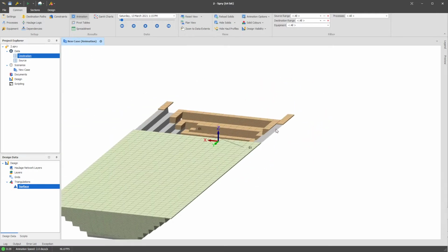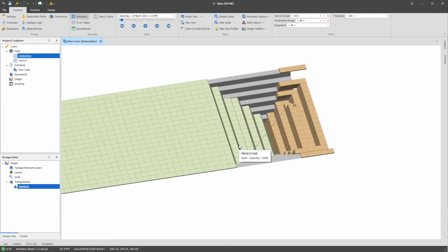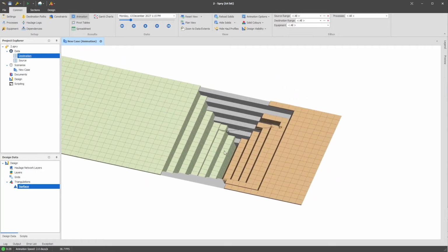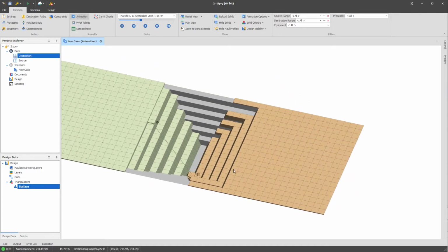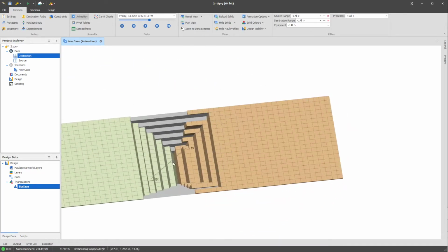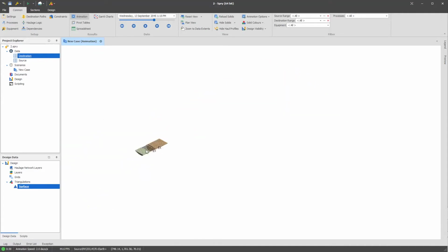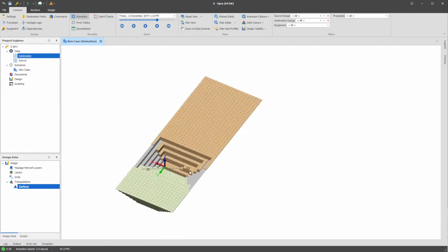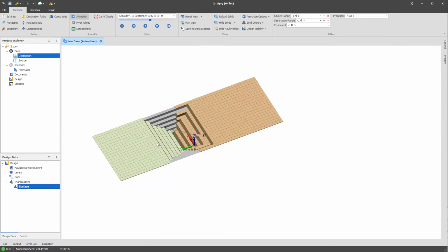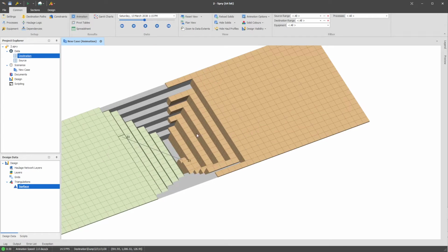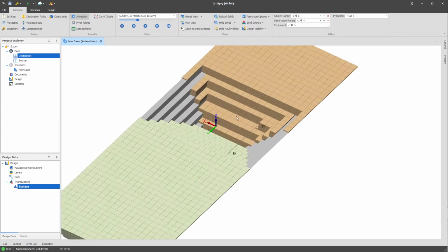I've generated a bit of a toy model for this exercise because it demonstrates a little bit better than the regular demo model does. It's a real basic toy that builds up over time. It has a few benches. You could envision a mid-pit road, and then a few different roads running along the sides of the pits. What I'm going to show you is how to get some semi-realistic starting haulage numbers for this using vectors and a couple of roads.